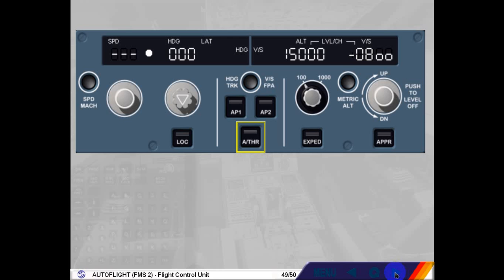See autothrust logic, e.g. as soon as takeoff power is applied. We will come back to these controls in a later module. Note, these push buttons may also be used for setting the APs and/or autothrust to off, but in normal operation this is not the recommended disconnection procedure.